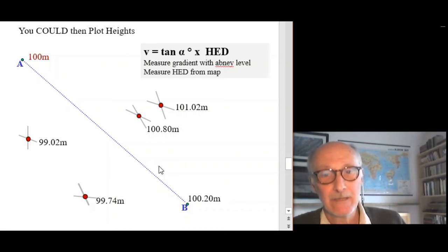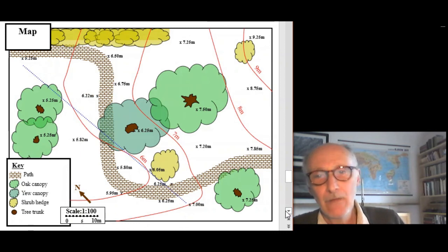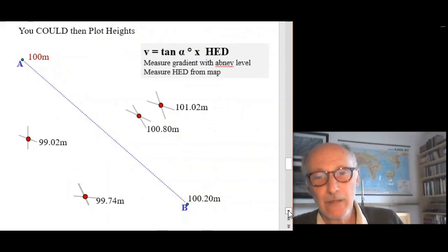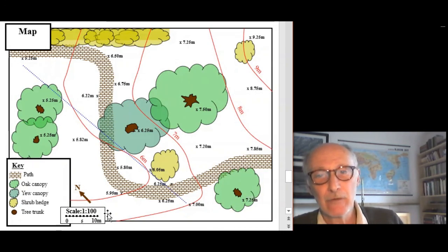So the plane table is a really simple bit of kit for doing those essential aspects of any kind of relatively small scale ground survey. It would be hard work using a plane table to map hundreds of square miles, but doing it in your back garden or at an archaeological site or on a river meander that you're studying for part of your geography dissertation or something like that, for small scale local area studies, the plane table is a really useful bit of kit. Once you've got that basic information that we've illustrated on this sketch, well then if you get enough dots and enough heights, you can join up the dots and create a finished map.